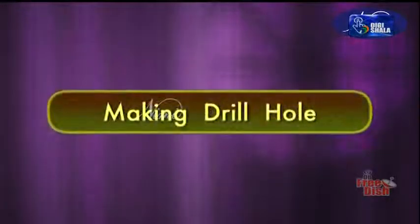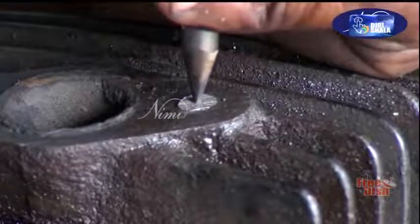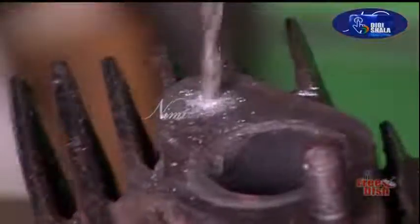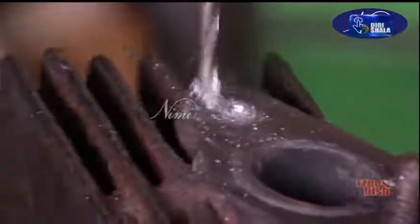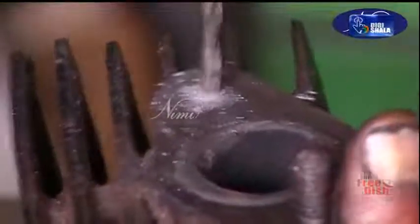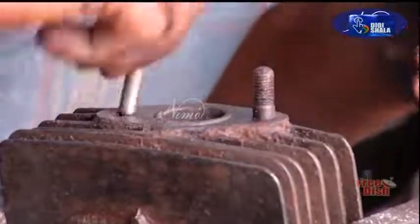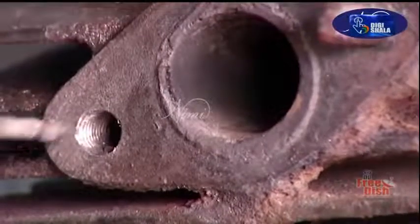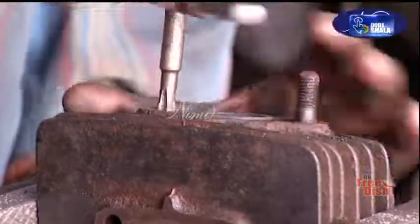Making drill hole. Correctly find out the center of the broken stud and drill a hole of diameter little less than the core diameter of the stud down the center so that the threads only remain. Remove the thread portion by the point of a scriber in the form of broken chips. Retap the drilled hole to clear the threads.